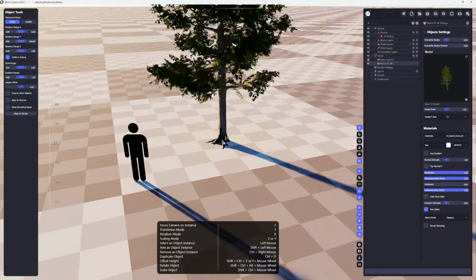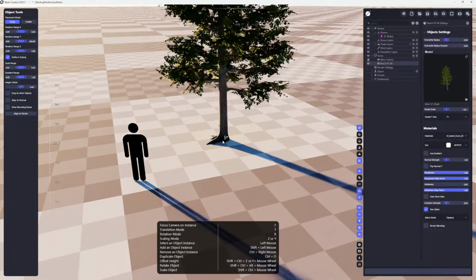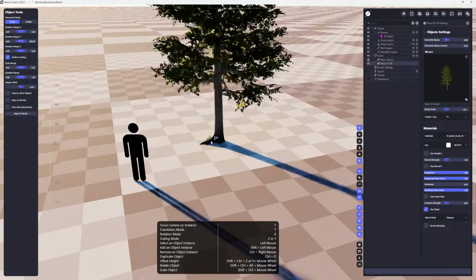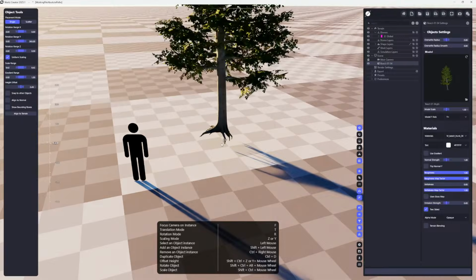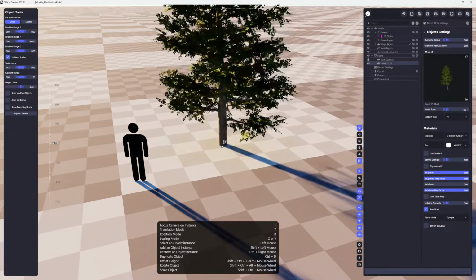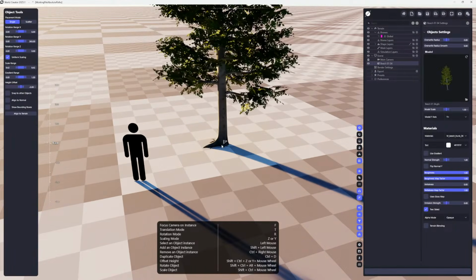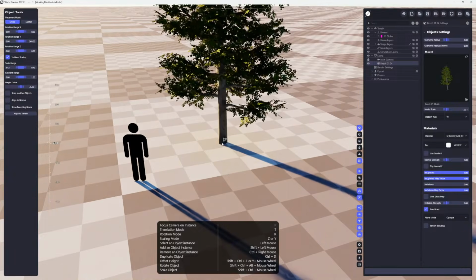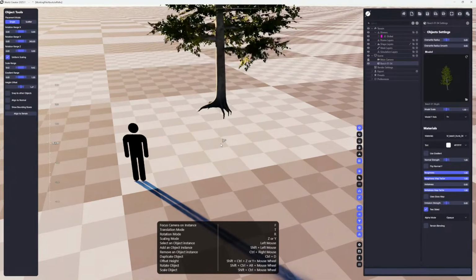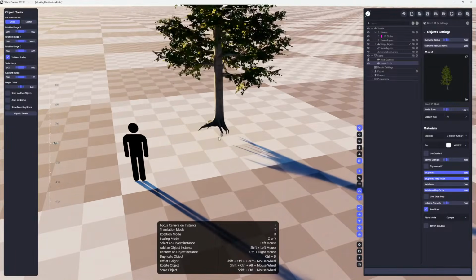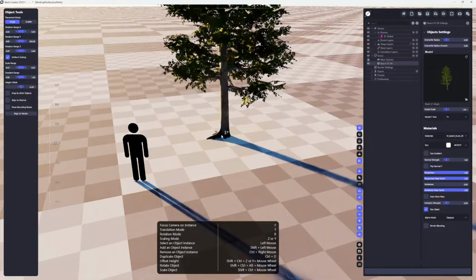It's kind of weird a little bit in the beginning, but once you get used to it, it's pretty simple. You can also move it up a little bit, along the y-axis, by holding the left control, left shift plus the Y key. On US keyboards I think it's the Z key, which is beside the X. That way you can place the object up and down. Sometimes that's pretty good because you want to have floating objects.